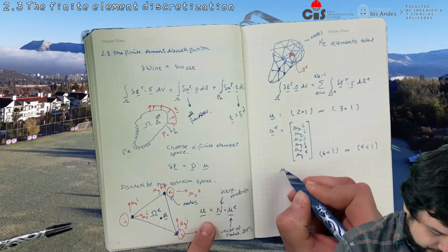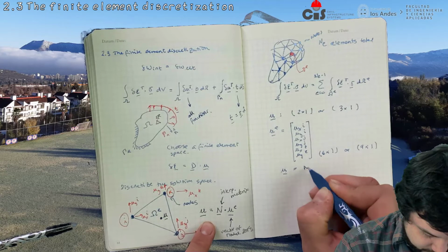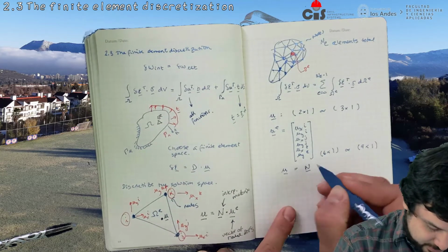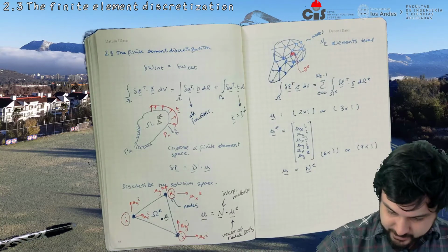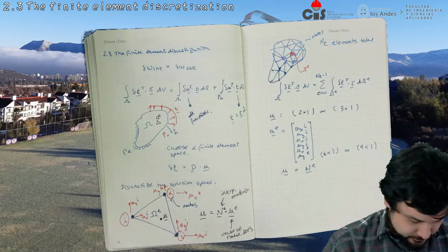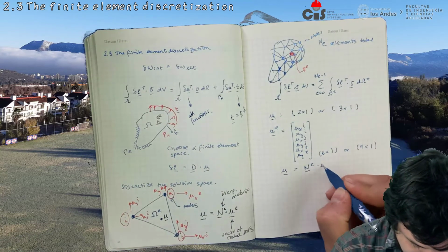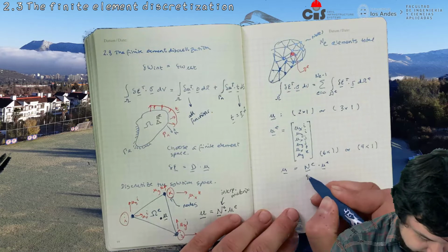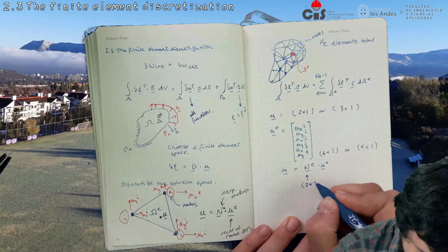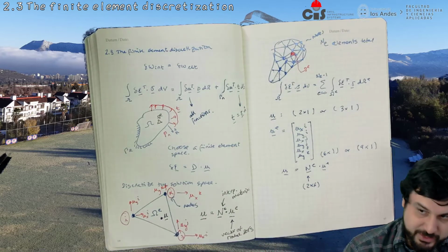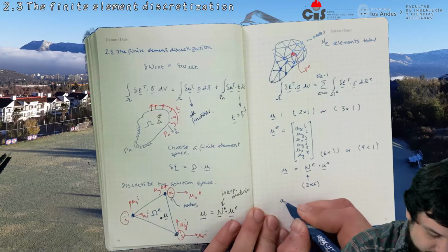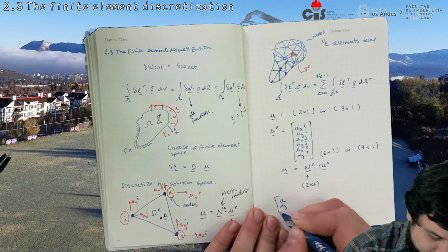Therefore, since u, the solution inside the element, is going to be equal to the element's interpolation matrix, let's stick to the nomenclature, times u_e. Then this matrix, the interpolation matrix, has to be of size, for example, 2 by 6 for this to work, or 3 by 6 if we're in 3D. And it's going to look something like this. So ux, uy at a given point.